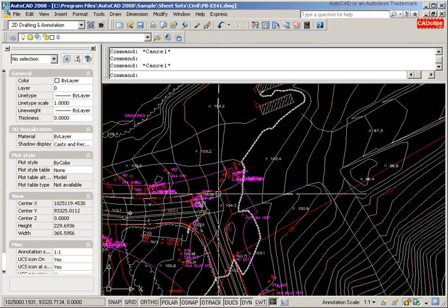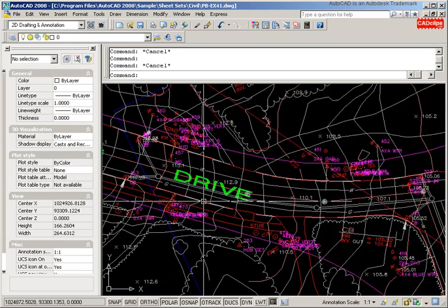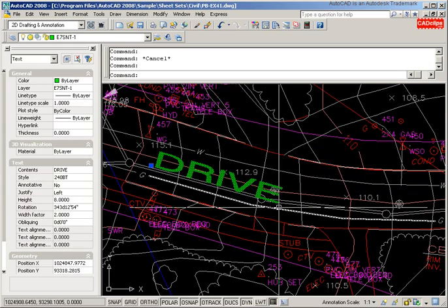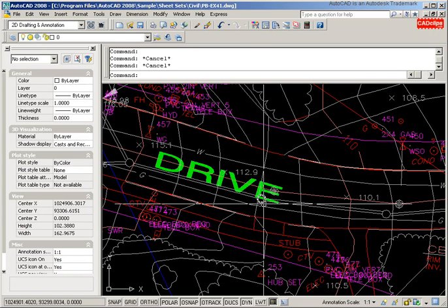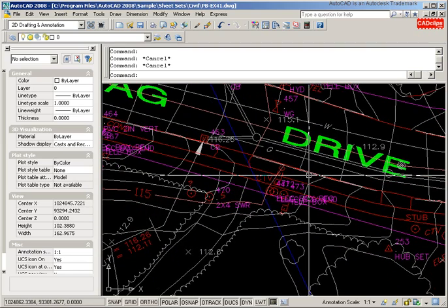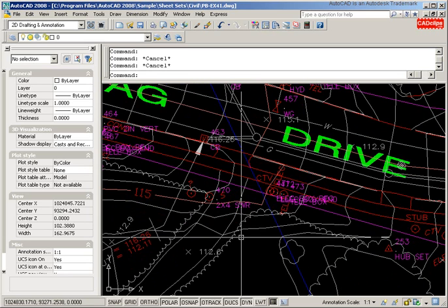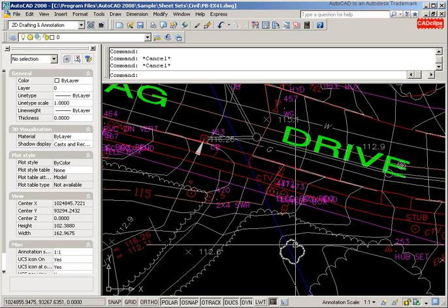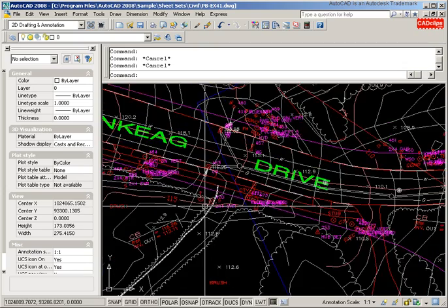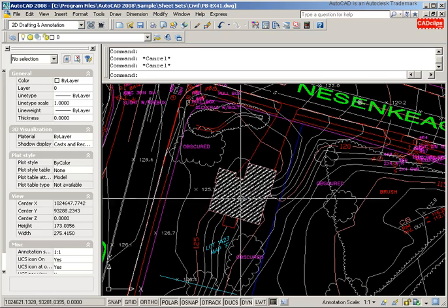So as you move around, depending on where you get your drawing, you will always be challenged with dealing with other people's layers. You'll never get away from that, depending on where you are in the food chain of being the CAD person. So we have to learn to understand how layers work and be able to flip them around and convert layer standards from one to the other in ways like that. And that's what really starts to speed you up.